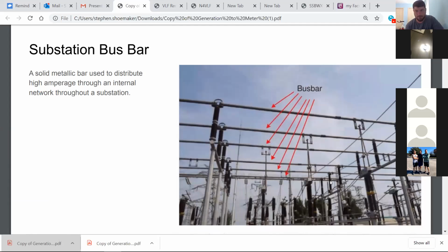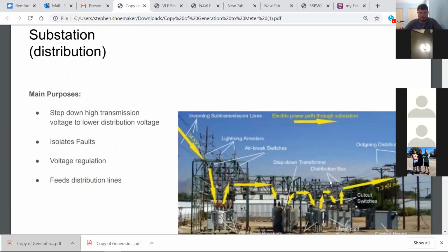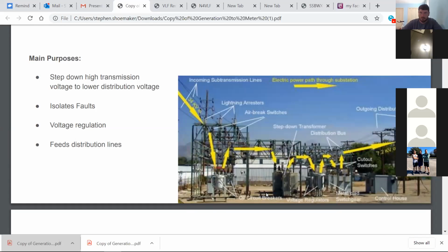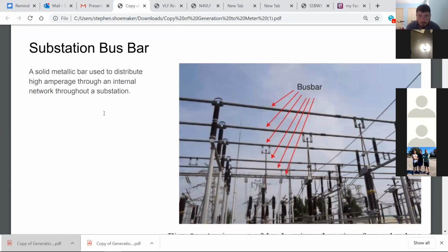It is in that picture from before, but the step down transformer just takes the transmission voltage and changes it to a distribution voltage. Right. And some companies do it in this fashion. We actually have a 34.5 kV incoming voltage. We'll have a breaker right here. Then we'll have it going out to the transformer. This transformer is going to take that 34.5 kV and convert it down to, does he have a voltage? He does. 7.2 kV. So here's your substation transformer. So there's a breaker on both sides, one to protect the transformer and one to protect the feeder circuit.